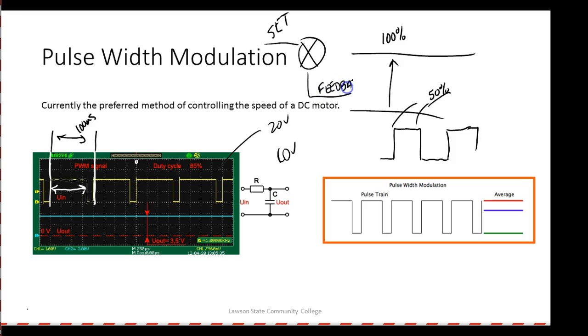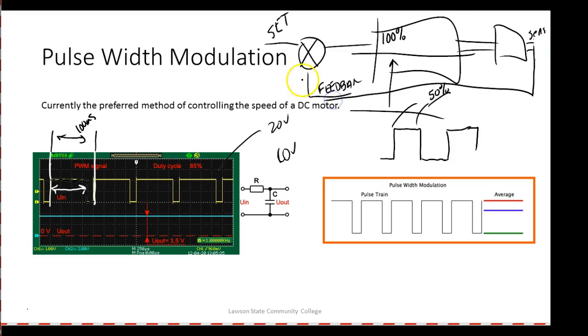Feedback. And then we go through all the electronics that run the thing. But out here on our actual actuator, we're going to have some type of sensor, and that's going to give us the feedback. So I put a set point in, that generates an error. Then it turns the thing on, and if the set point and the feedback don't match, what does it do? It either speeds it up or what? Slows it down. And a perfect example is the cruise control on your car.